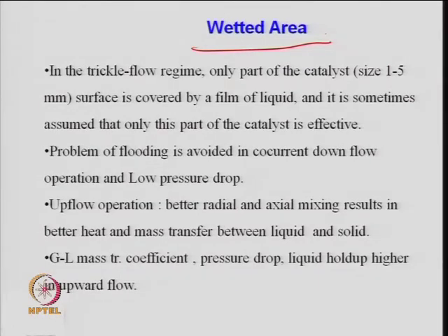So, this is again an important parameter in terms of the design of a trickle bed reactor, or how to improve this wetting, if you need a high wetting or high wetted area. Again, when you are in the trickle bed region, the catalysts are generally of larger size. This is one thing. The surface is covered by a film of liquid, as I said earlier, and we assume that this part is effective for catalytic reaction.